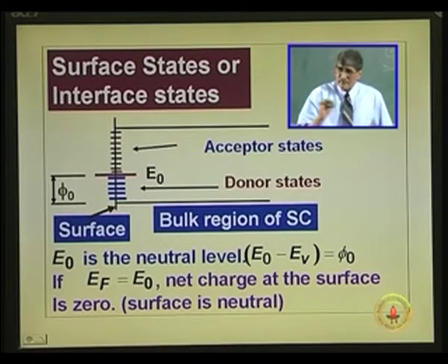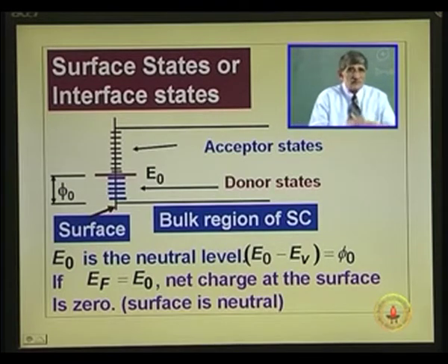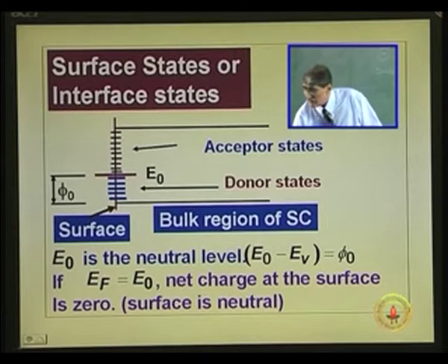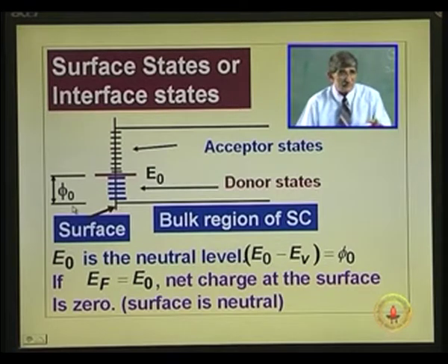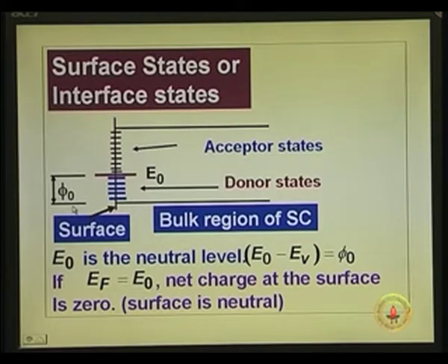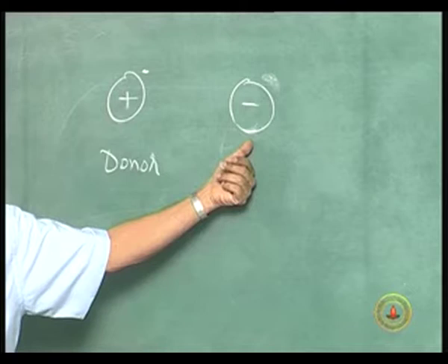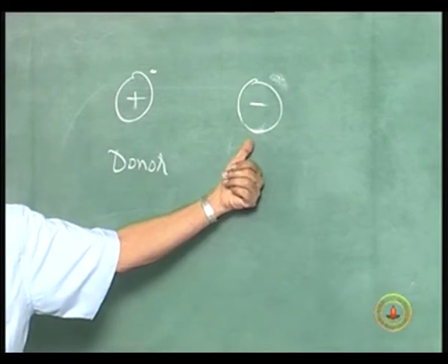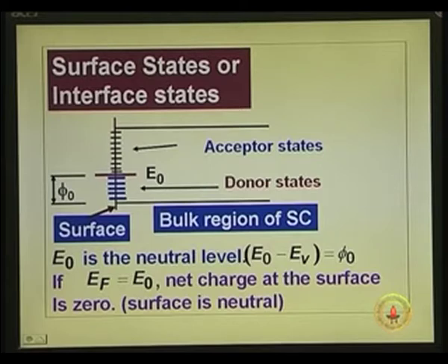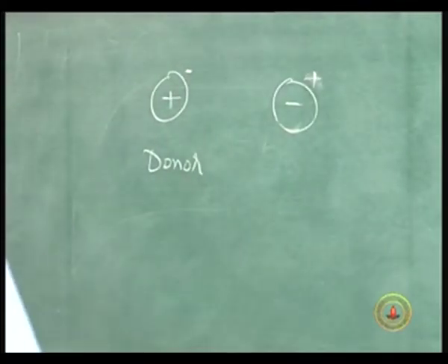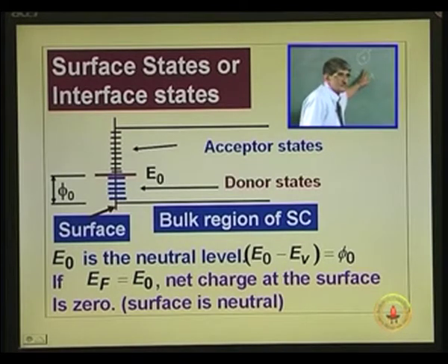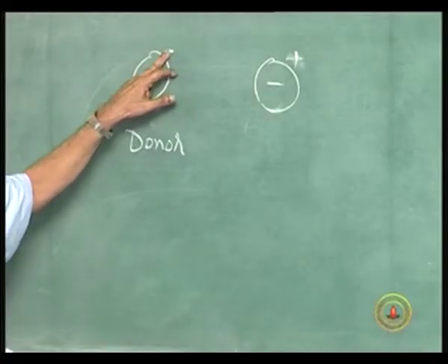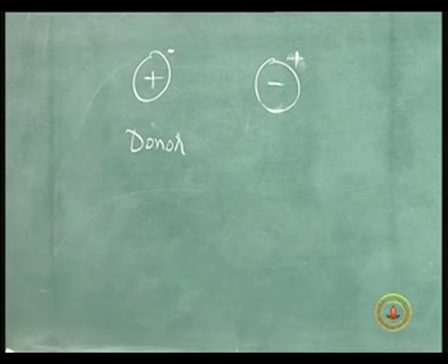So, if the Fermi level, okay, is that clear enough? It is very simple to understand, electron occupying, not occupying. Okay. So, if it is occupying below this donor level, it is neutral. The acceptor level, if it is not occupied by electron, it is neutral. If I remove that, it is occupying, negative. So, if it is occupying, it is negative. If it is not occupying, it is neutral. That is the understanding. So, it is simpler to visualize with the donors, because that is a physical thing. Electron not occupying, it is positively charged, electron occupying, it is neutral.